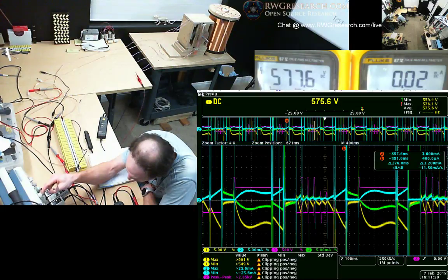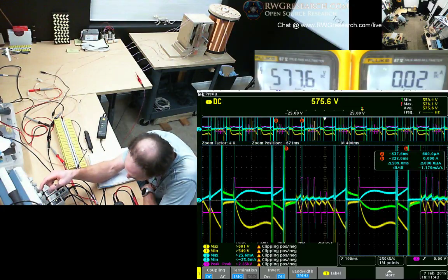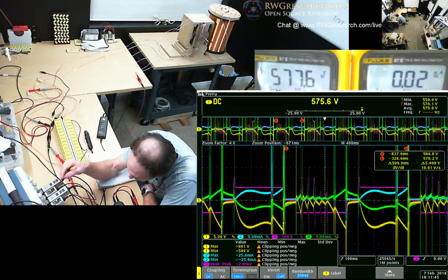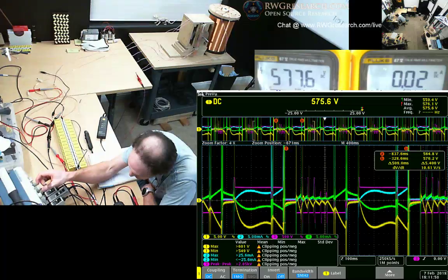So we'll call it there, and we're gonna call it right here. Let's turn it on yellow so we can see what we're seeing. Pretty close, 509, so it's a little fast, but we only did half the commutator anyway.